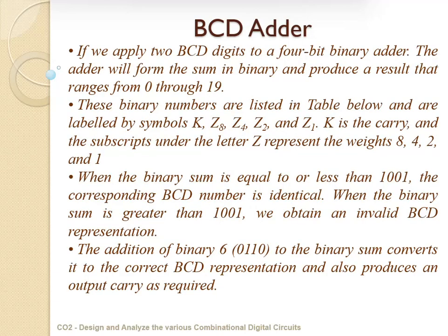And next we move on to the BCD adder. So we have 2 different classifications. One is called binary, which starts from 0000 to 1111, or we can call it 0 to F. When it comes to BCD numbers, it includes only numbers from 0 to 9, that is 0000 to 1001. So numbers greater than 9 cannot be represented directly using BCD. In such a case, each digit has to be represented by 4-bit values.